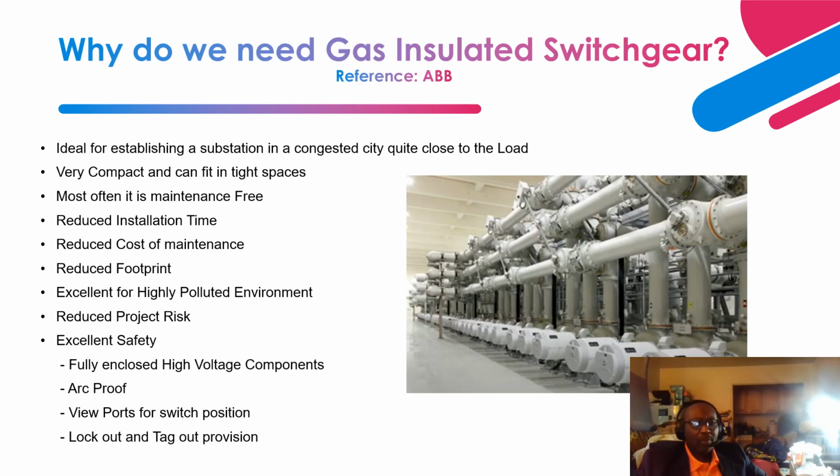Next slide. Now let's take a look at why we need a gas insulated switchgear. There are a myriad of reasons that need to be understood by any discipline engineer to understand the need for implementing and applying a gas insulated switchgear. The first item is that it is ideal if you need a substation in a congested city, right?